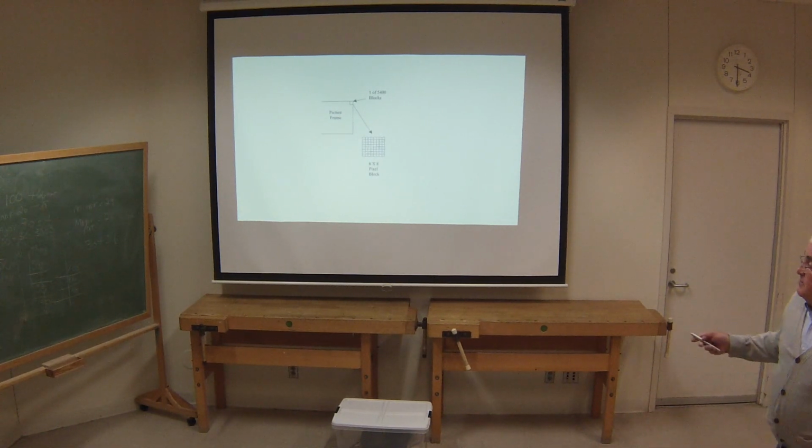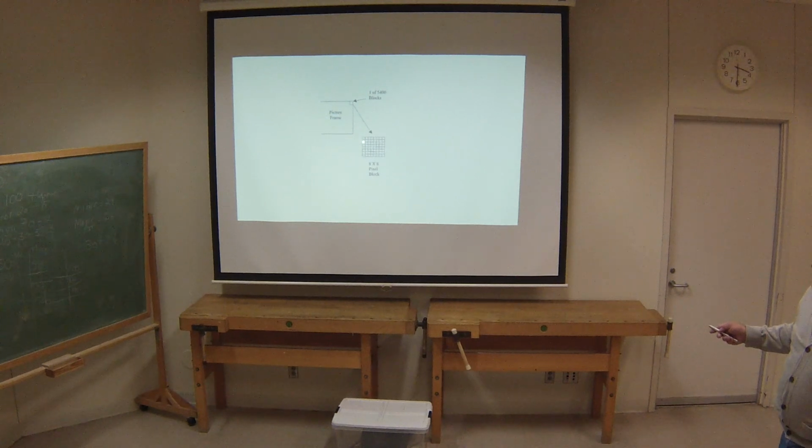This block is the data in this block here, and this is confusing because each block represents a word, a digital word, which represents the frequency of the sample. So those little blocks in your 8 by 8 block are not pixels. They represent a pixel that has a spatial coordinate on the screen. Correct.